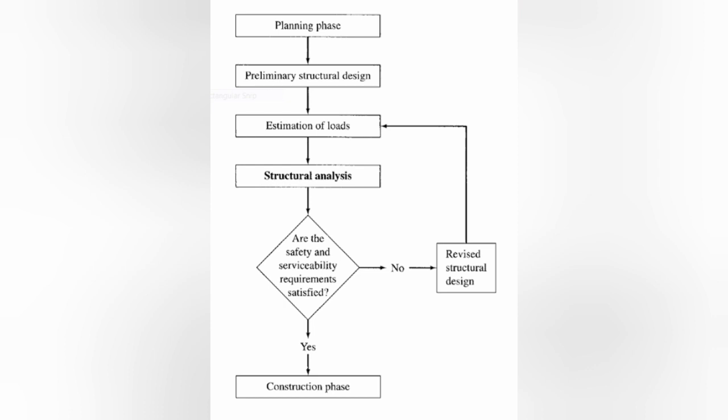Why do you go back to the estimation of loads? Because you will redesign the structure. You will change the dimension. You will change the size. You will change the quantity. With that, there's also a change in the weights. There is also a change on the effects of the loads.